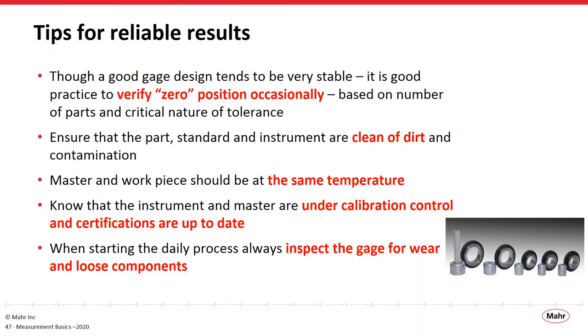With any gauging operation, we talk about gauges and measuring tools. It's good to bring a caliper back to its contact or back to zero every time to make sure that nothing has changed. With the micrometer, or with a variable gauge, it's good to put the gauge standard, the master ring or disc, onto the gauge and re-zero it, because you might get some offsets over time, temperature changes, dirt, and so forth. It's critical to re-zero occasionally and do that throughout the day.